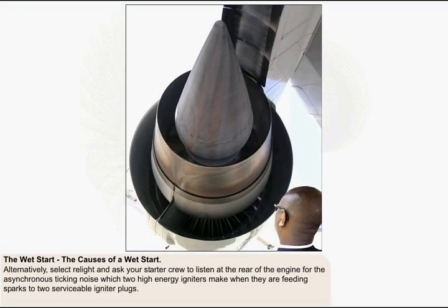Alternatively, if your starter crew trust you, and if it's safe for them to do so, you could direct them to the rear of the engine, and having selected relight, ask them to listen for the asynchronous ticking noise which two high-energy igniters make when they're feeding sparks to two serviceable igniter plugs.